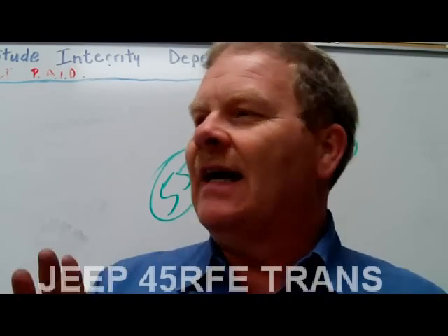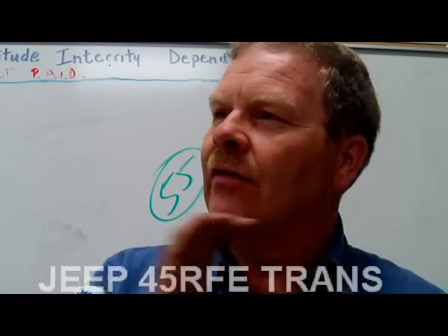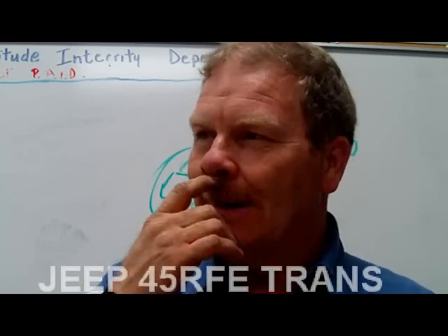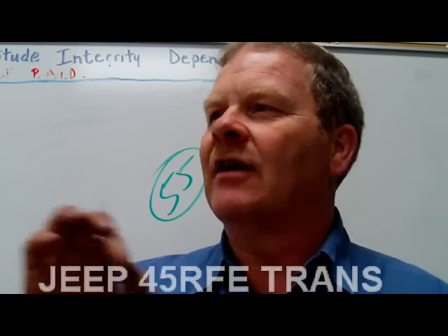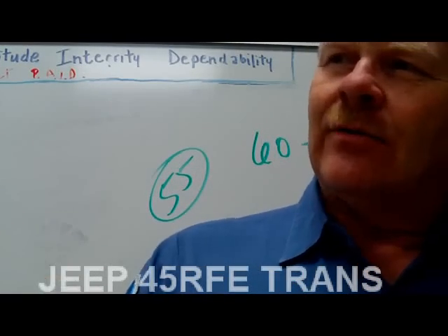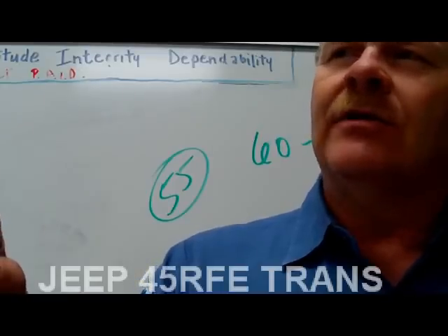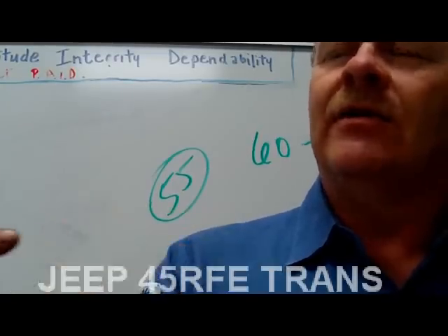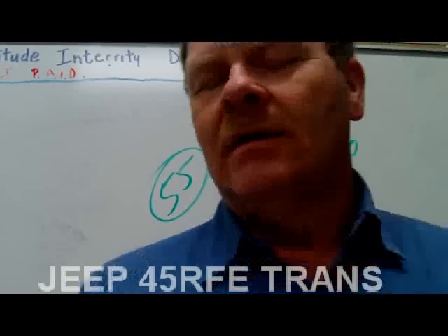But it doesn't have a clutch in the torque converter on that one. Everything was done down inside the transmission. But it had an extra shaft coming out. You had the stator support, you had the turbine shaft, which was hollow, and then coming out the middle of it, you had that shaft that went right down into the middle.